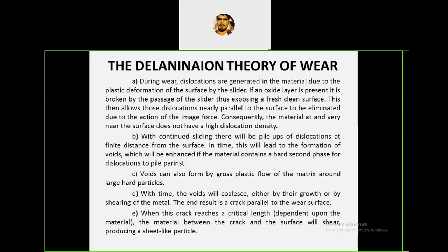In any mechanical component, we cannot eliminate the point crack. Because of manufacturing defects or the surroundings, there is one small source for a crack. If we apply the load on that crack, that point will start growing. It will start propagating into the specimen, and ultimately once the load exceeds, it will fracture. Correct? Here also, same thing. First, there is plastic deformation.